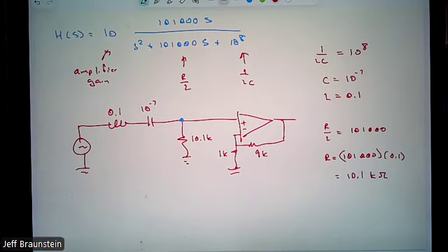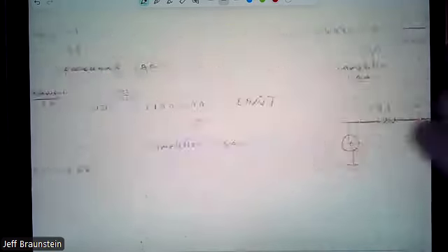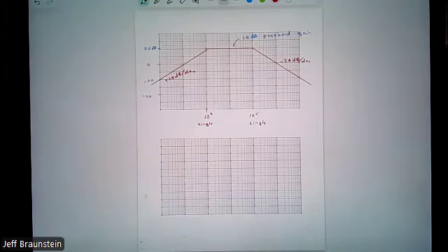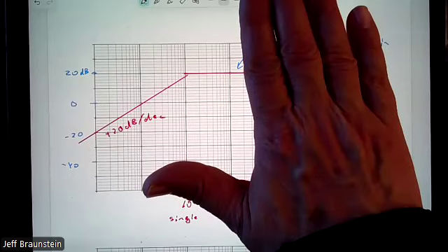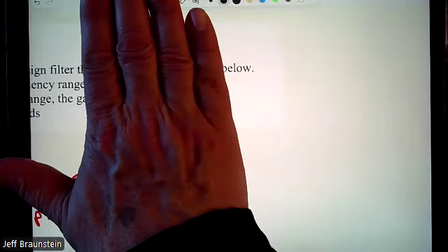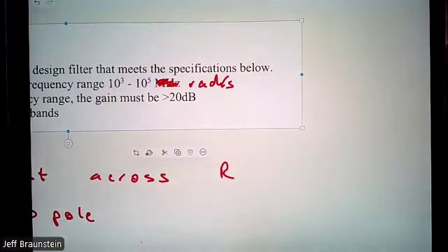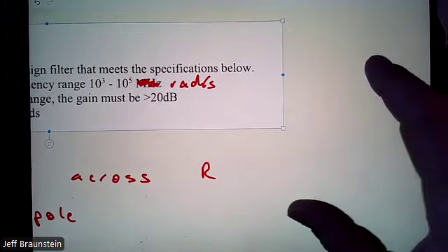There's something that's not great about this. Before I dive into that, I want us to think about other ways to design this. If I take this filter response and just look at that, what do we see? What would you call that? It's a high pass filter. If I just look at that, what's that? Low pass filter. So we can always make a band pass filter by cascading low pass and high pass filters.